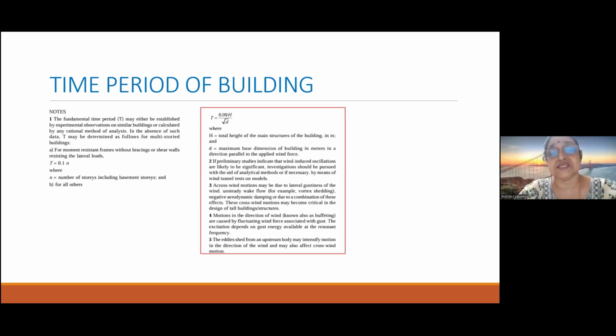Another important aspect is the damping of the structure. We know that damping is something which takes out the energy which excites a particular structure, and every structure has some inherent damping. But in the case of wind, what happens is that it gives more energy to the system. That is where the divergent amplitude of oscillation, like galloping or flutter, happens. That is, some negative aerodynamic damping effect is there in such cases. But in some cases, the wind will have a positive effect on the aerodynamic damping, an added damping to the structural damping also. So the wind will have both favorable and unfavorable conditions with respect to the oscillation of the structure.